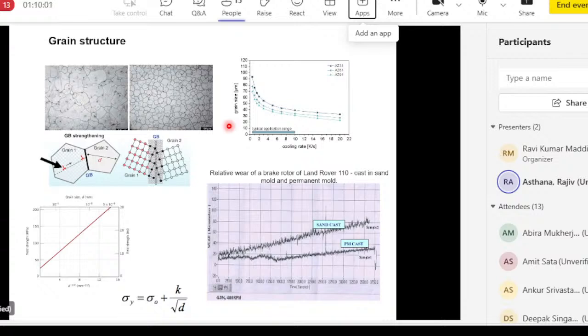And then you can also make grains fine by using high pressure. Like in squeeze casting, when the metal solidifies under very high pressures, grain structures become fine because of large undercooling and also because of very good thermal contact under pressure, contact between the mold or the die and the casting. So there are different ways to get fine grain structures to get high mechanical properties.